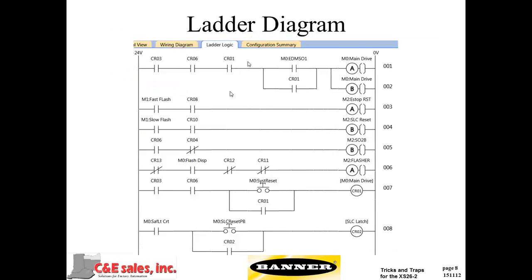Okay. This is a ladder diagram which is generated during the time that we're doing the programming, and it again simulates what the logic that you have built using the Boolean functions would look like in a ladder diagram. Here again, we see the value of the various function blocks and logic blocks having their own name, so that CR02 has a functional name which is the same as that latch in the functional view.